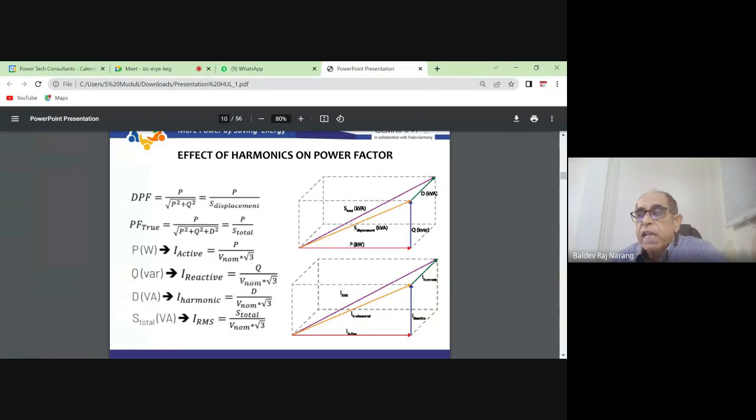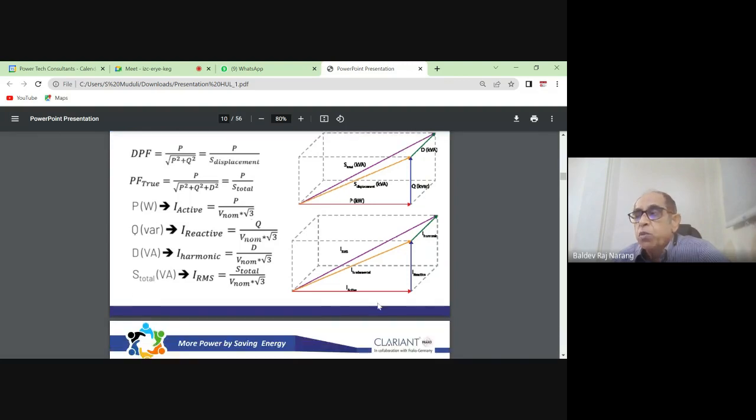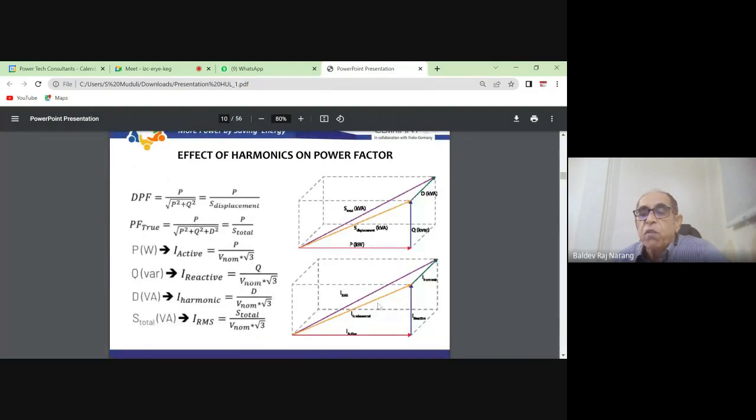But the problem is they are having difficulty changing over to these structures. They need time. They need the meters to be recalibrated. They have to find out the waveforms, and it is a long process. So it is going to come, but we have to be prepared that we can be asked to pay for distortion. We can be asked to pay for leading power factor. So we cannot avoid that. As an energy auditor, you should always say: maintain your harmonics within limits, maintain your leading also within limits.